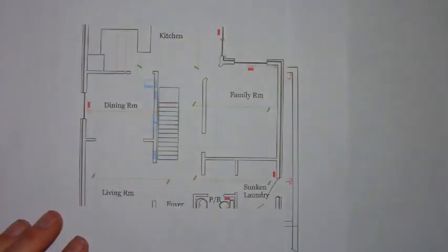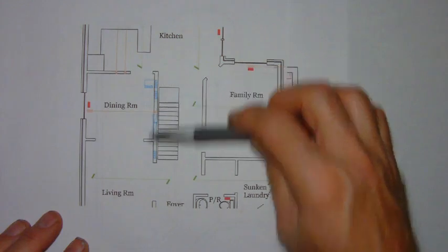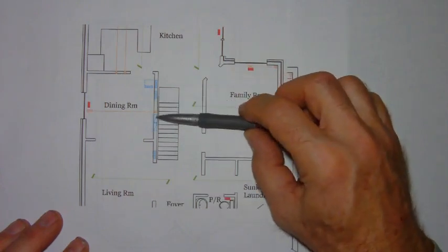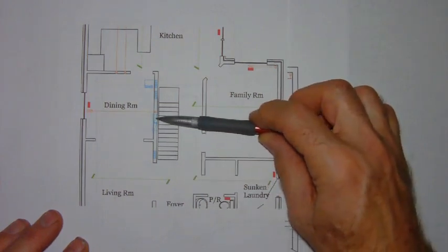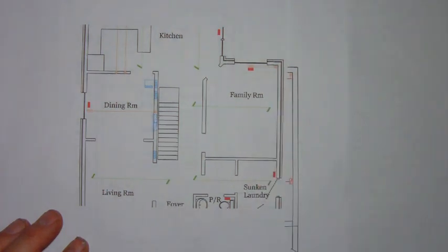If you compare that to the plate opening in a 2x6 wall, the 2x6 wall would be 14 by 5.5. So there is quite a bit more free area in the plate opening on the first floor. This allows us to then get more airflow through each individual plate opening.